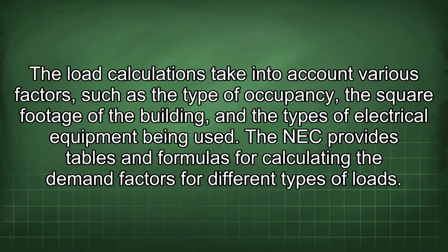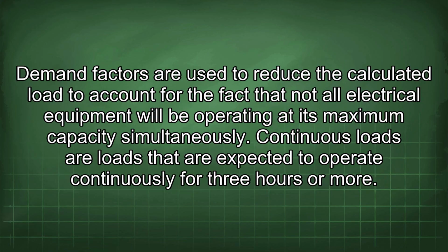The NEC provides tables and formulas for calculating the demand factors for different types of loads. Demand factors are used to reduce the calculated load to account for the fact that not all electrical equipment will be operating at its maximum capacity simultaneously.